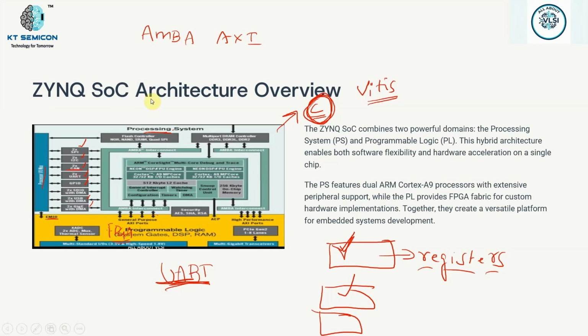The agenda is very simple. If you want to have communication between your processor and this particular IP, you are going to use another tool, not Vivado, which is known as Vitis. Normally embedded developers use this to develop the drivers and so on. They use this software, Vitis, to develop an application using C or C++, and communicate with these IPs.